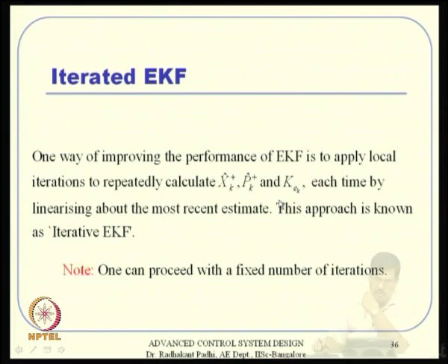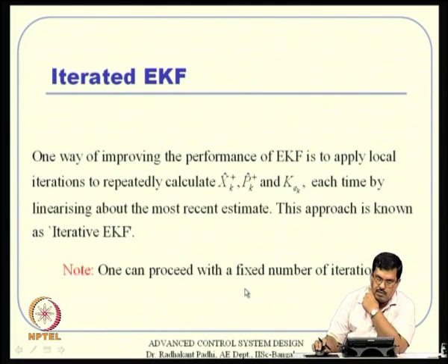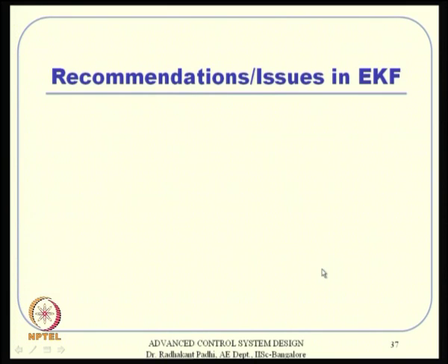This is the whole idea of iterated EKF, and one can proceed with a fixed number of iterations. You do not have to really wait for convergence. You can simply use some 2-3 iterations before you proceed further. Remember, these are real time computation issues that should be addressed also, because without that this has no meaning. So, we can use it based on a fixed number of iterations, then go to the next step.